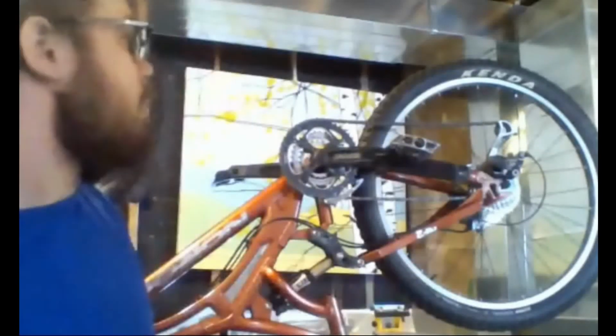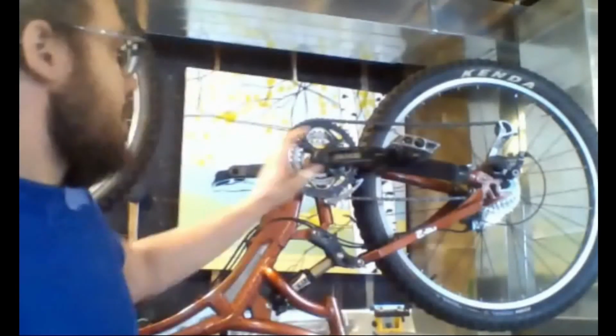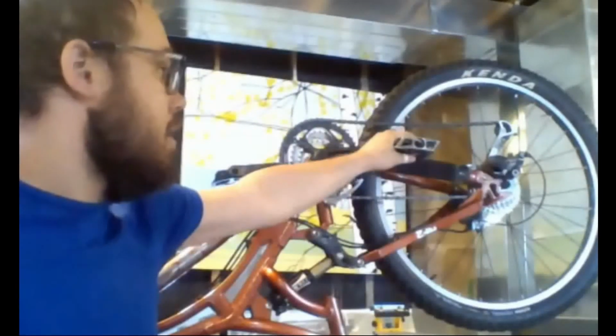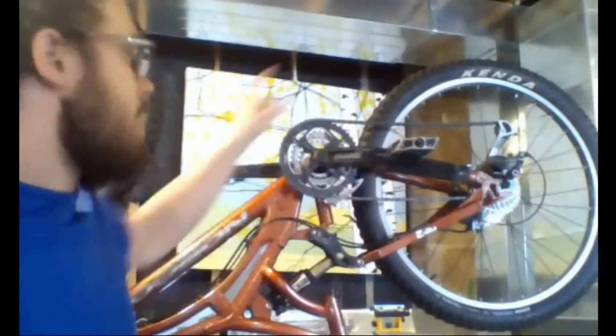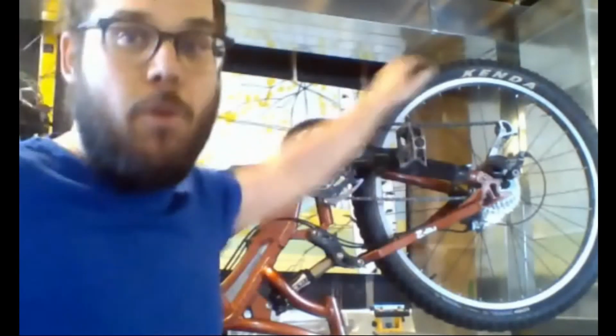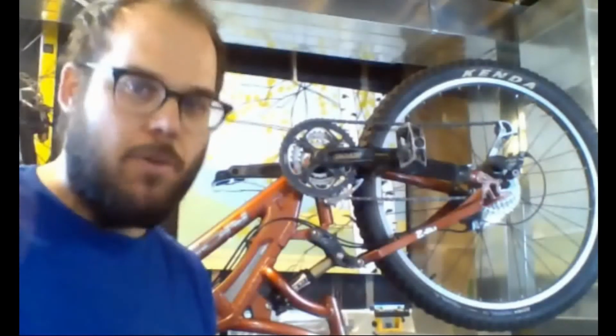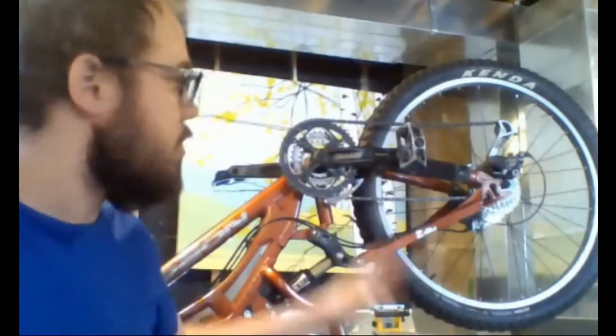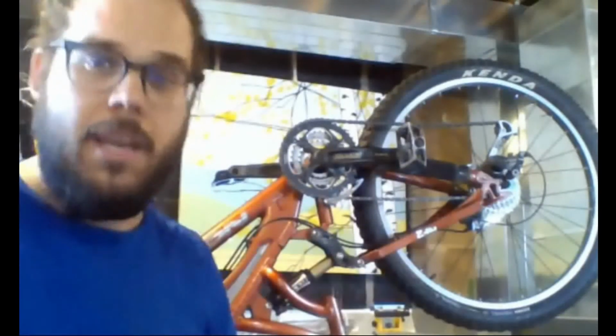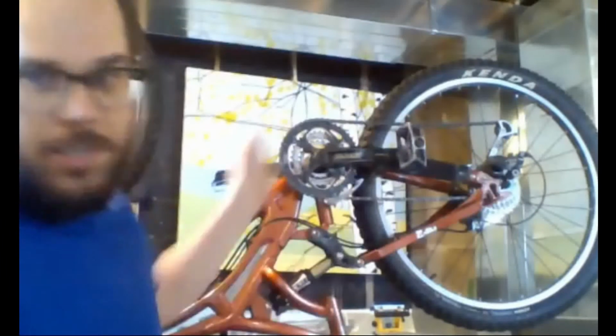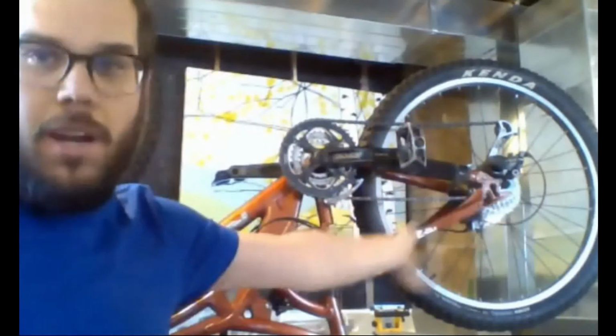So what we notice here is that every time I do one rotation of this part of the system, I get 4 rotations of the wheel. So there's a 1-to-4 ratio involved there right away, right? Every time I pedal once, I get 4 turns of the wheel. So again, that's going to make me go quite quickly. The disadvantage is it's actually quite hard to turn this system just even on its own against its own resistance.